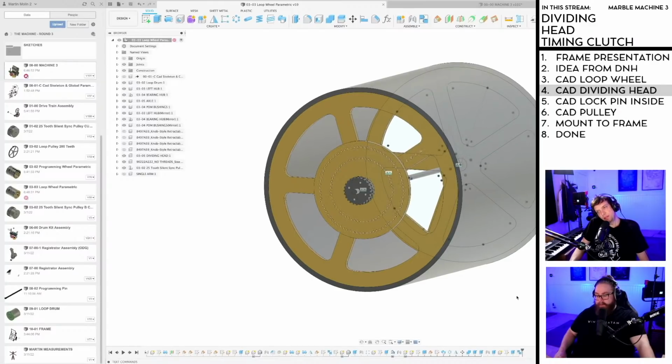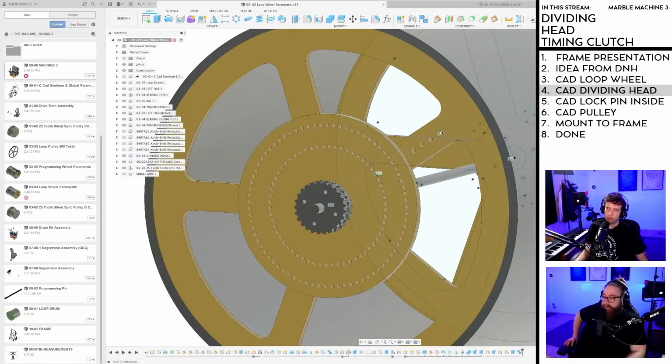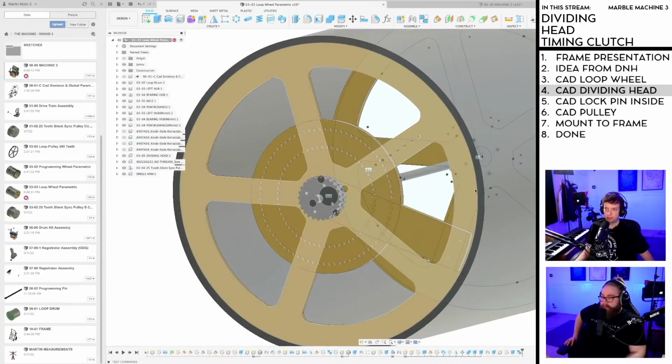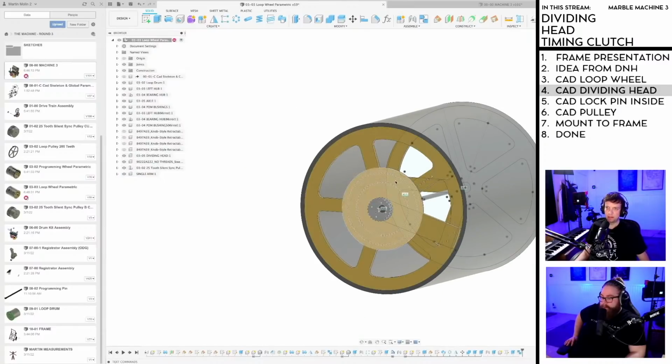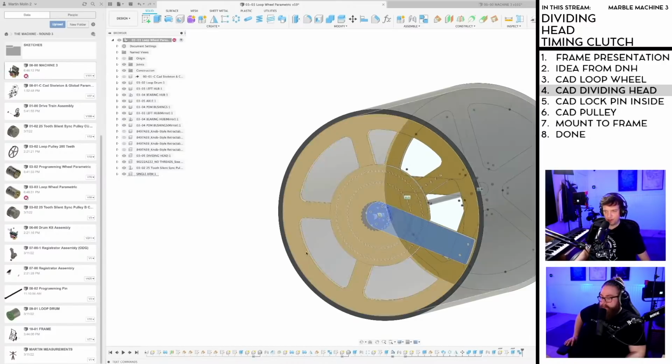But if we do that, yeah, and the reason why we would rather do that than having the arm is because with the arm we would need to put 1 million threaded inserts, and over here we have screws. Now the disc is the better option, and we don't have to stretch inside. This is good. This is okay. We're getting there, everyone.